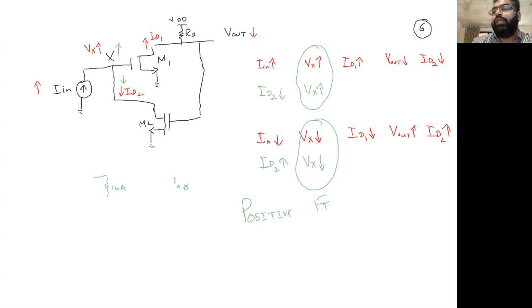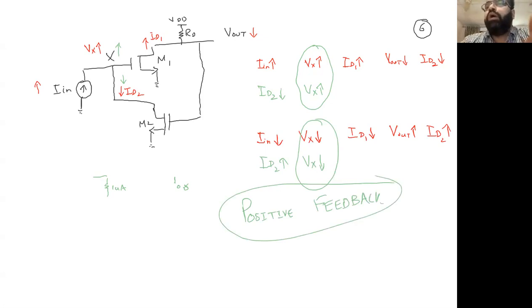And as we mentioned previously, we use positive feedback in analog circuits or in digital circuits mainly for oscillator development or for the creation of latches and memories, where we want to hold the value for a longer period. So just make sure you explicitly revise these examples. First of all, do these 3 examples which we did in the class, and also go into the book. There are a couple of solved examples and there's a problem. So do those problems and clarify these negative and positive feedback concepts.